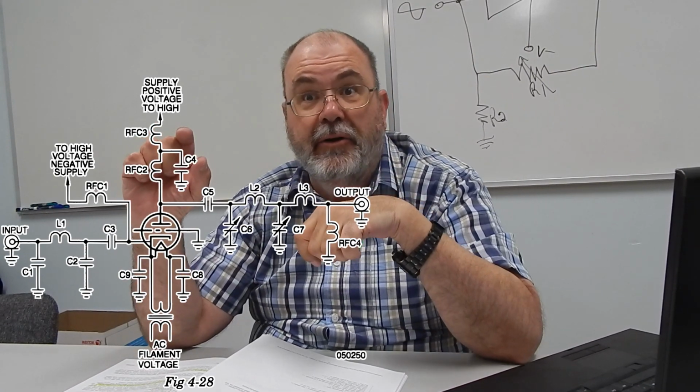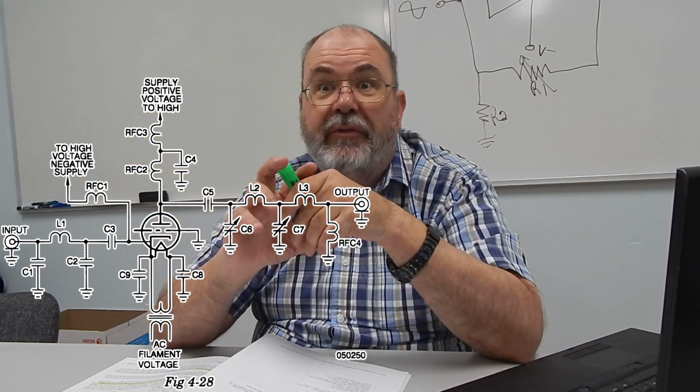Now, in the RF world, we use positive feedback and oscillators to our advantage because we want to create frequencies, okay? But amplifiers are supposed to amplify, they're not supposed to oscillate. And once again, a length of wire that long can actually pick up some of our signal and feed it back into the circuit. So we can have completely unintended, stray feedback paths that we never thought of. And oops, my 1,000-watt amplifier, oh yeah, it's putting out 1,000 watts at 55 megahertz or some frequency way outside the band.